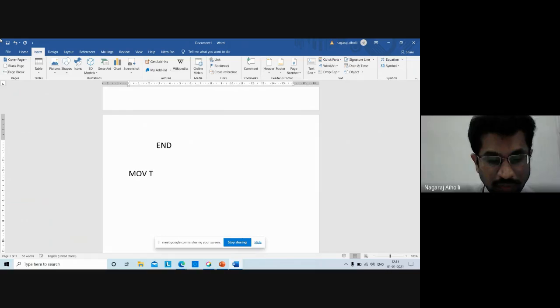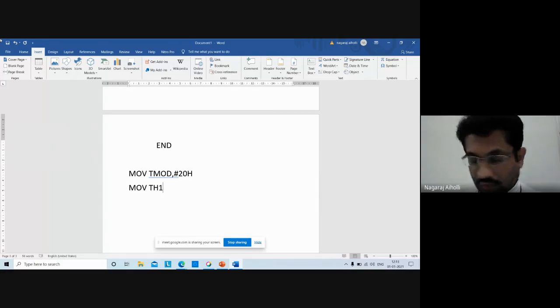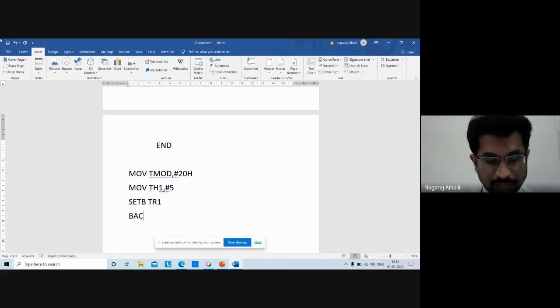MOV TMOD, #20H. MOV TH1, #5. SETB TR1. BACK: JNB TF1, BACK.